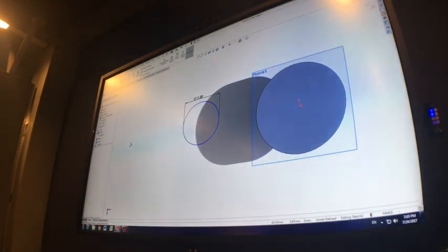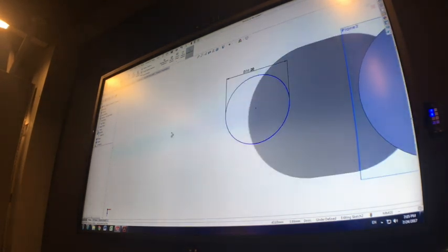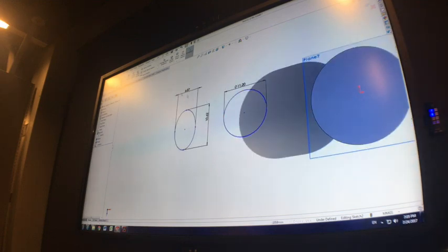When you sketch or start an ellipse, it starts with a center point and you drag out. It looks like a circle, but once you've clicked again, you drag the other direction, you can see the difference between the two. And with the ellipse, you can actually dimension between those points to define that shape. That's the difference between the ellipse and the circle there.